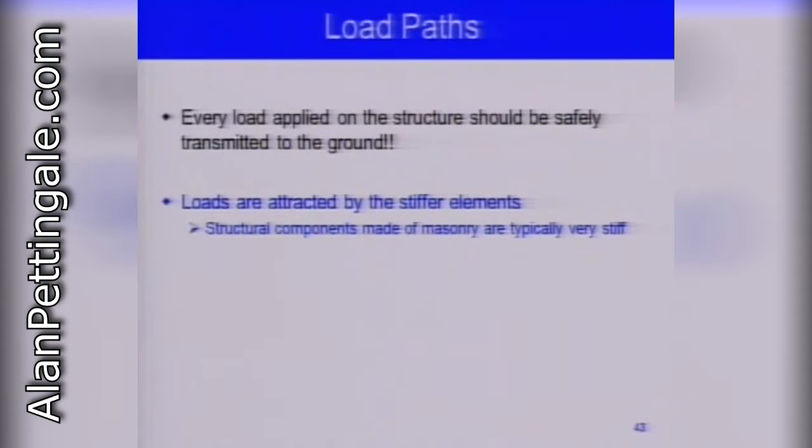Then what's important for every structure, whether you're assessing an existing structure or designing a new one, is to make sure there's a very clear and strong load path provided. We want to make sure that every load, whether it's gravity, so that's vertical, or lateral, wind, earthquake, or whatever, has a clear path to reach the ground, and then we're safe. As long as the foundation is also good.